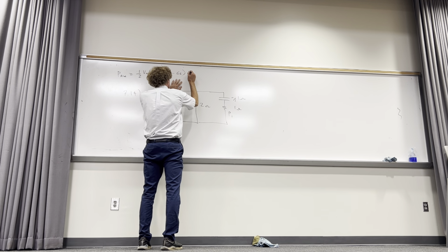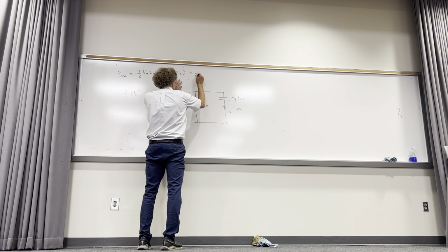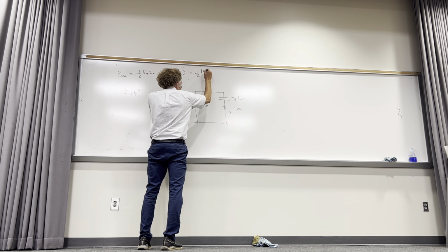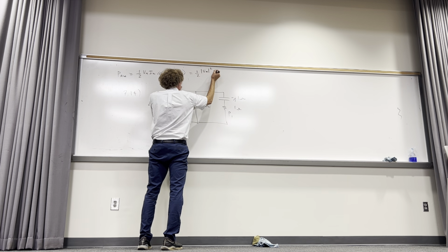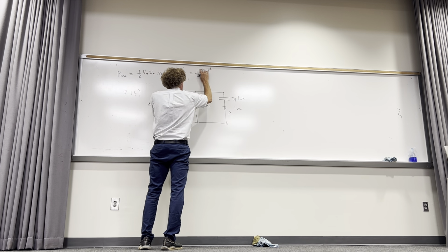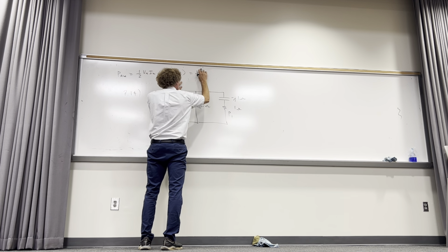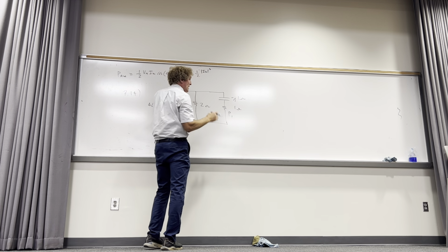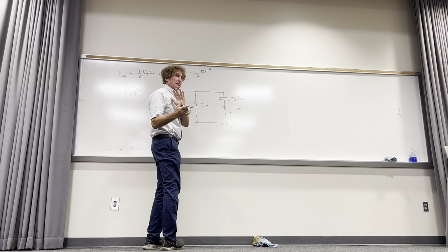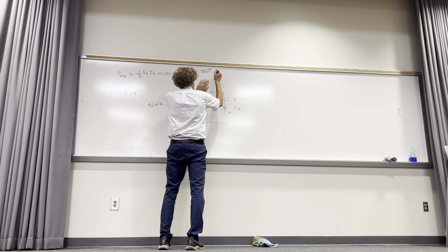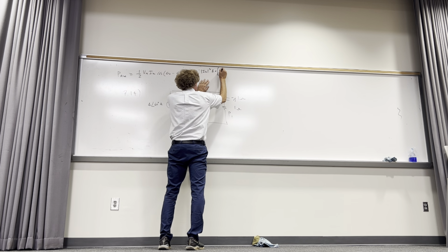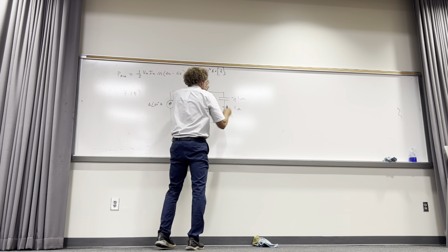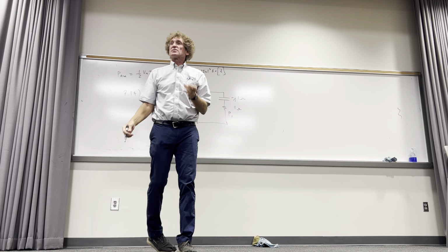It's also equal to 1/2 the magnitude of the voltage across the element squared. Well, I'll tell you what, I'm not even going to put that one down there. What I'm going to do is this. It's 1/2 the magnitude of the current. Now it's magnitude, so you have to take the magnitude. There's a real and imaginary part. Magnitude of the current squared times the real part of the impedance of the element. And the real part, if it's just a resistor, is just the value of the resistor.